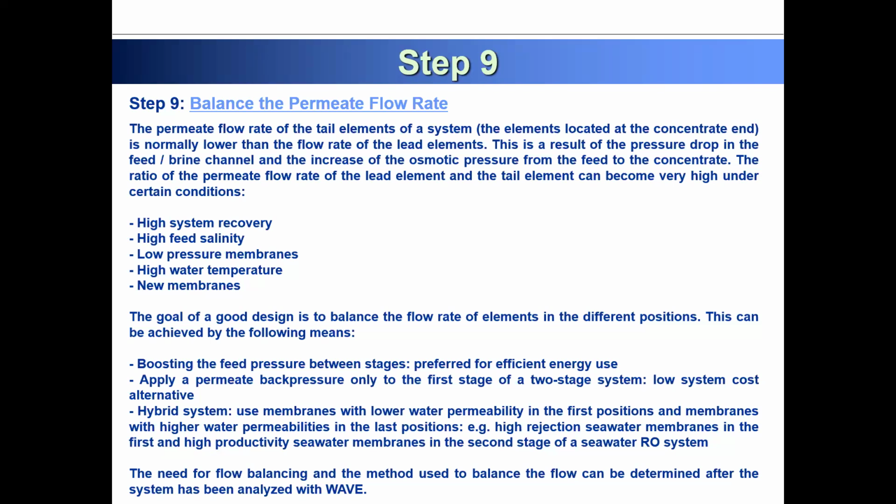So you can have your final product and prefer efficient energy use. Also, apply permeate back pressure. So if you have too high a permeate pressure, you can provide a back pressure only to the first stage of a two-stage system.